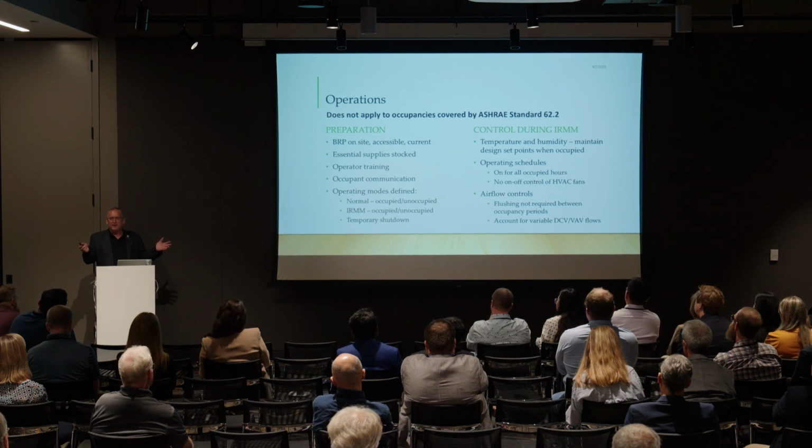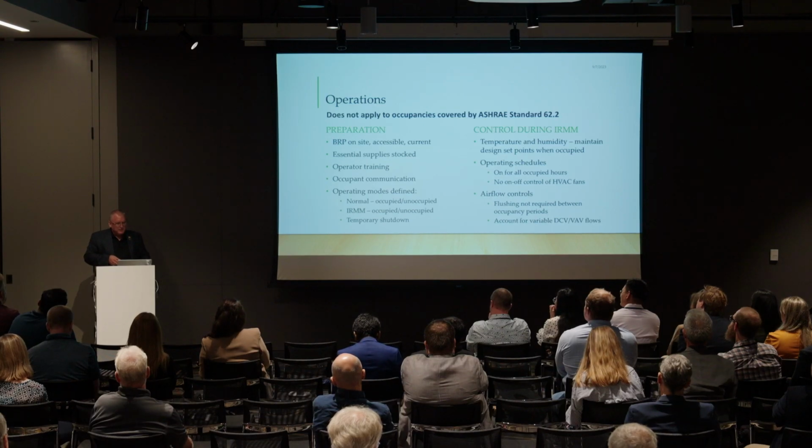Actually, I do that at home, right? I have a typical DX system at home. I could put into auto mode and the fan would go on and off whether cooling was needed or not. I just run the fan all the time because I've got MERV 13 filters in my air handling unit, and it cleans the air all the time.